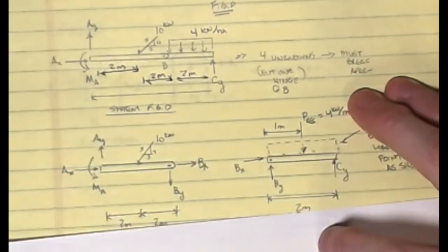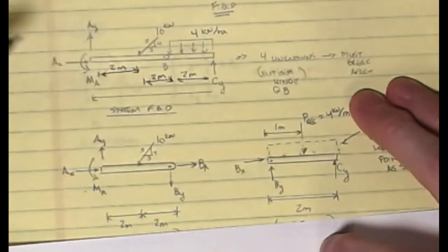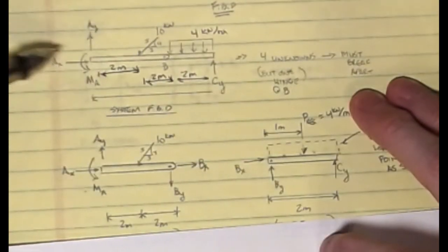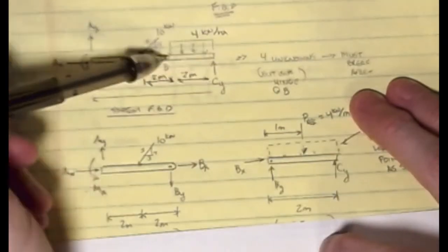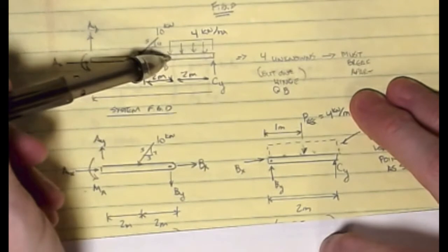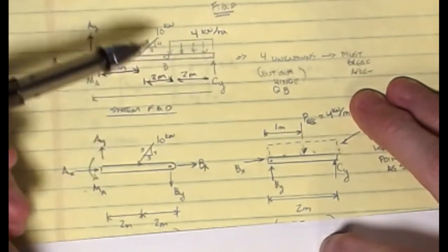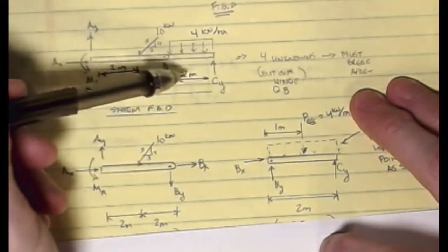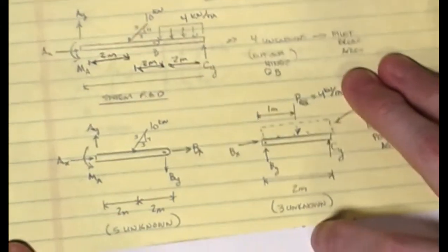All right, so we recognize that our system wasn't a truss, because this is fixed, so that's clearly not a truss. This one was pinned here and rollered here, so that met that requirement, and it's straight, but the problem is that this load is not applied only at the hinges. So this goes into some sort of flexural case, and we've got to be able to go into that.